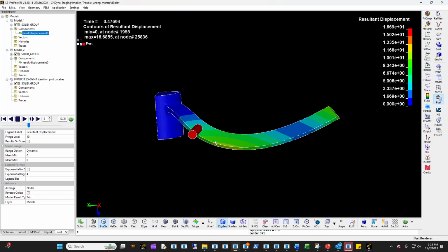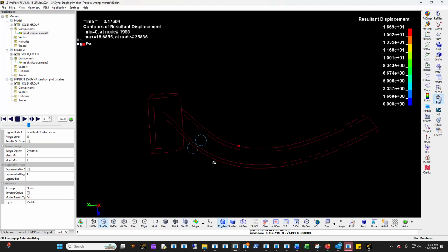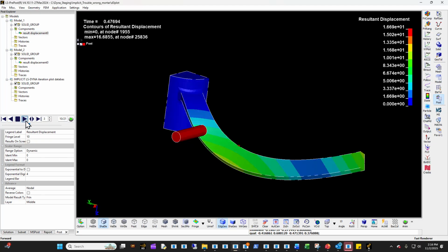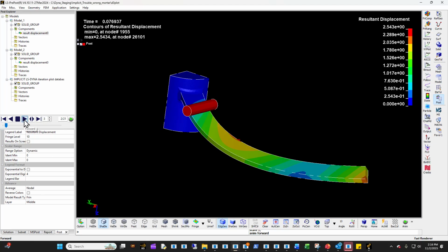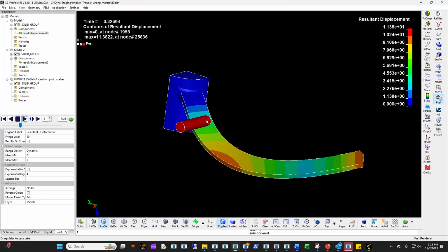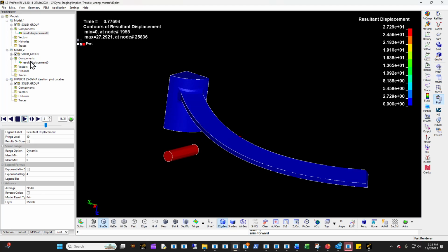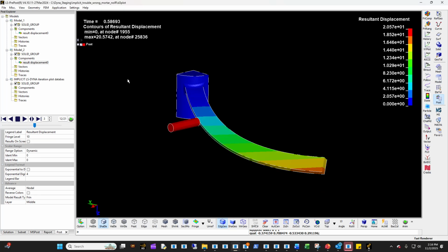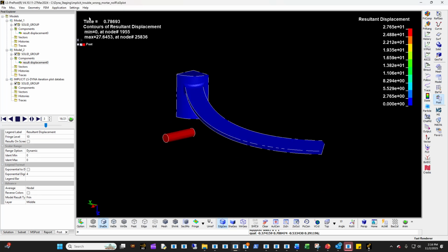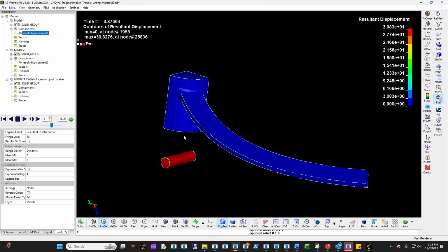This is the one with the mortar contact, and this is the one with the bar going this way. You can sort of see there's some really weird things. And it's doing that. So you can sort of imagine you can even get this thing to converge by doing some kind of model that looks like this. On this side, it does something a little bit similar, but in this case, I don't have any inertial relief, so you can still get this thing to work. But you can sort of see the deformation is slightly different.